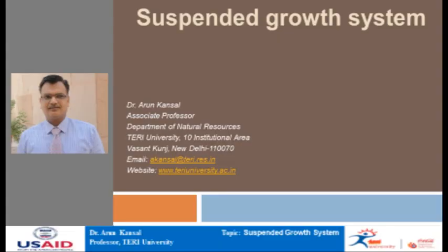We will discuss suspended growth systems, that is, aerobic systems in which microorganisms are suspended in the bulk of the liquid media. We will discuss certain basic fundamentals which are applicable for suspended growth systems. Amongst the suspended growth systems, the activated sludge process is the most widely used, and today we will discuss the fundamentals of these systems in the context of the activated sludge process, and the modifications of the activated sludge process.